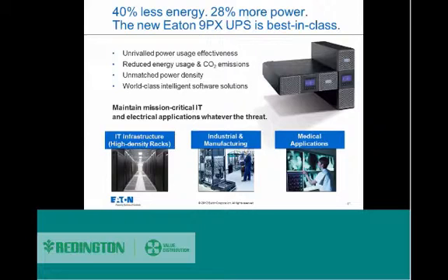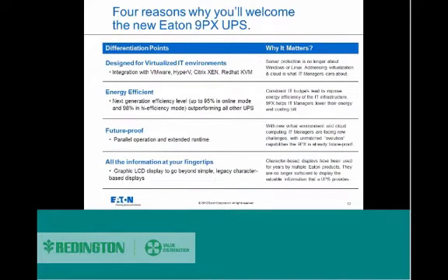Being online, it provides you protection from all the 9 power problems which are usually there. Just to name a few of them, if there's frequency variation, if there's harmonic distortion, if there's line noise, and then over voltage or under voltage or surge protection. These are just to name a few, but all of them are actually being protected by this class or series of UPS systems.